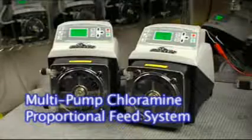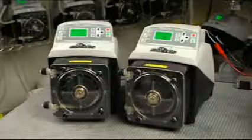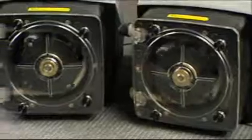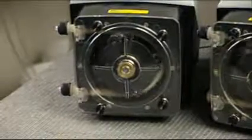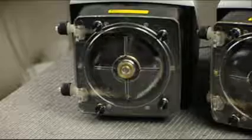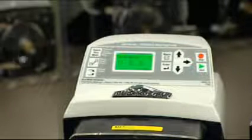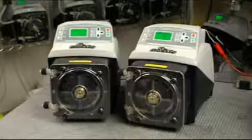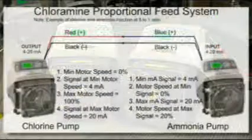In a chloramine system, chlorine and ammonia are injected at a ratio of approximately 5 to 1. Using the A3's 4 to 20 milliamp analog output signal, or the 0 to 1000 Hz digital frequency output signal, a primary A3 pump can be used to drive a second A3 pump in direct proportion to itself. In this way, should the primary chlorine pump fail to inject, the secondary ammonia pump will automatically stop.